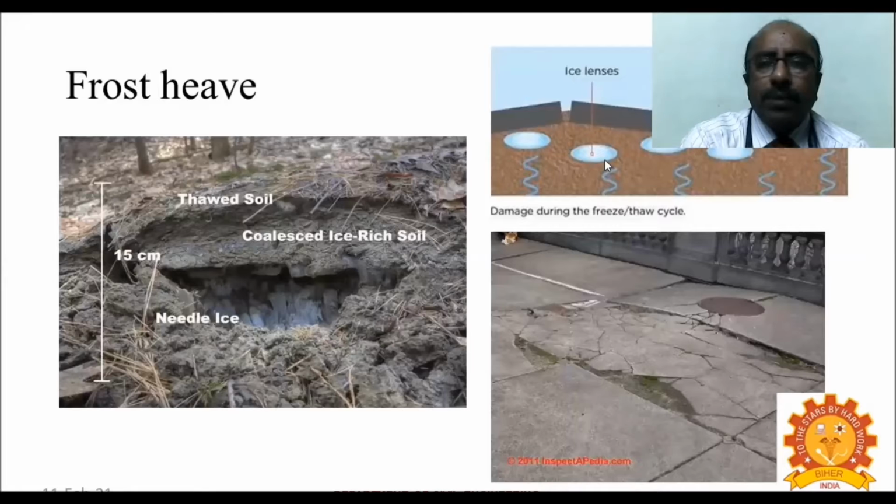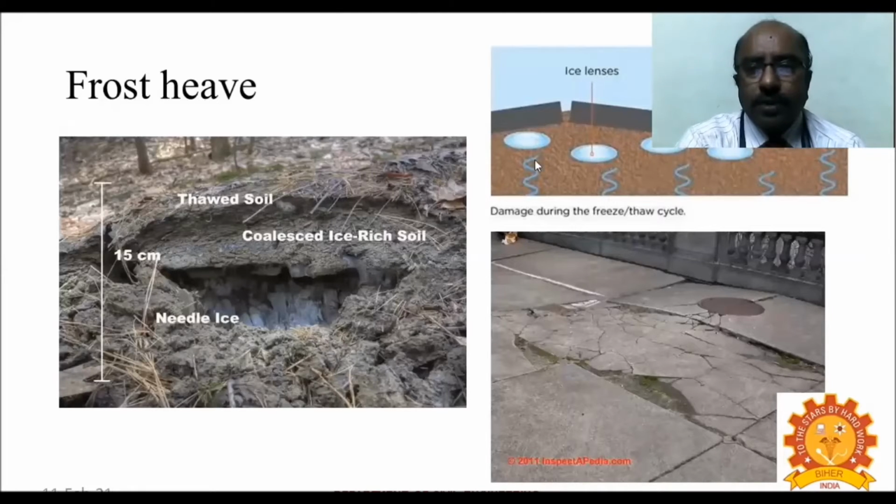That is, the water vapor becomes ice. When it becomes ice, the water increases in volume, exerting pressure on the soil. That is why heaving occurs. It is called frost heaving.